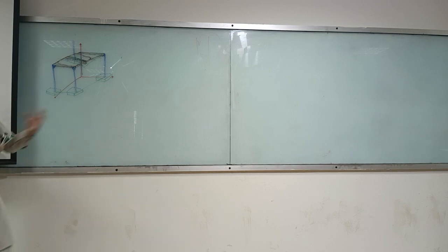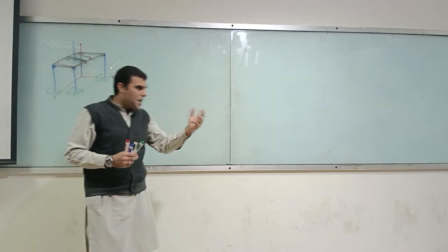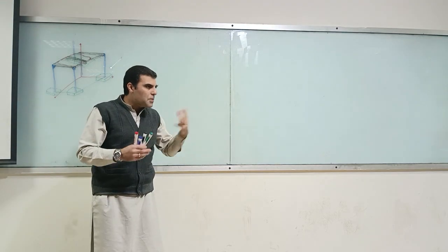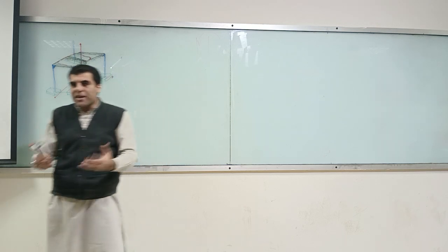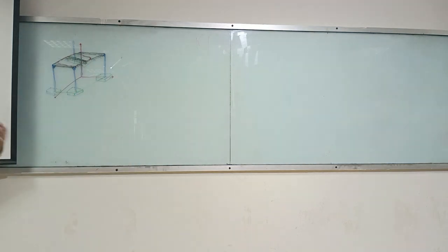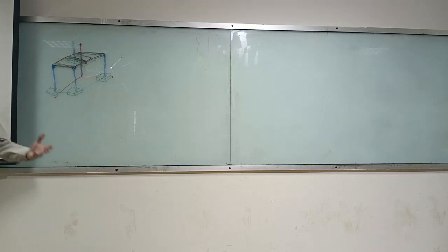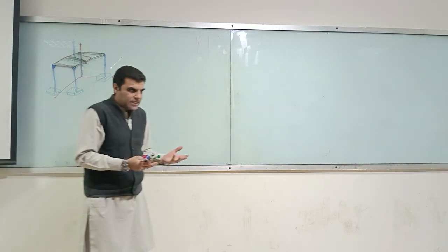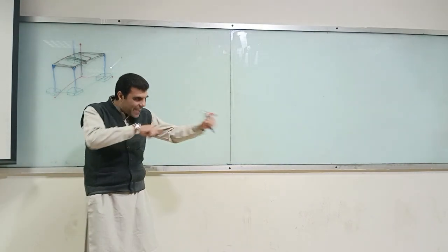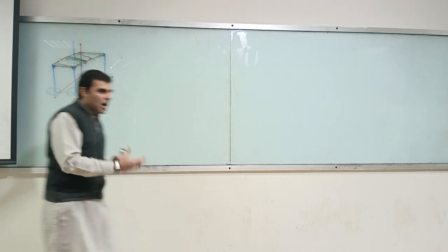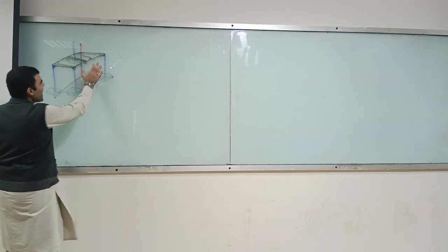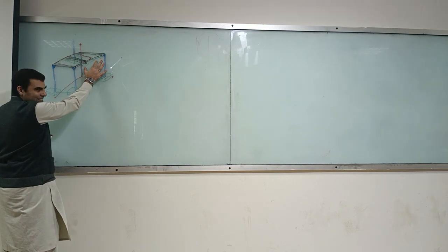Yes, sir. Look, I have found the area load, isn't it? Now my load is, for example, some units per unit area. What would be the unit of my load, which I found now? The load of you people. That would be in, say, kip per feet square or kilonewton per meter square, something of that order of magnitude. Now it has got area because it's per unit area. Now what I would do is I would multiply that with this length.